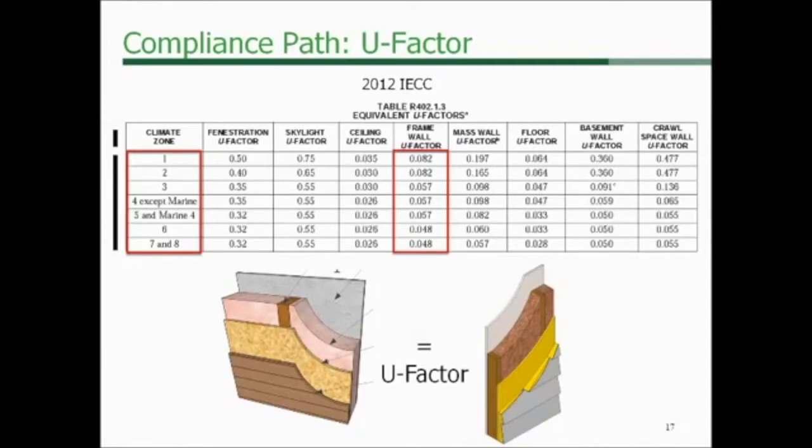So what this basically says is, look, if I have two different walls, this is my base wall, and if I have two different walls, say I'm using insulated siding or whatever it is, and as long as it's equivalent, it's okay. It's the energy performance. Okay, as long as it has the same U factor, I'm okay.